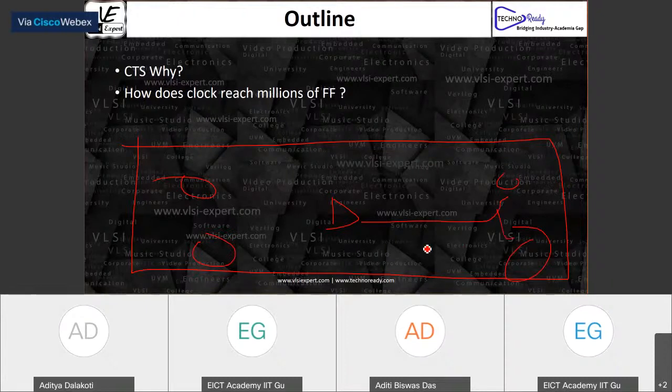And if this wire is too big, then the slope of this would be bad, right? But why do you care if the slope is bad? Didn't you guys till now study that as long as the clock reaches symmetrically, then you can time this thing with respect to this thing? You have to minimize the skew. That's what you said, right? But wouldn't the rise time and the pulse width be the same? It's a symmetric wire to all of these.